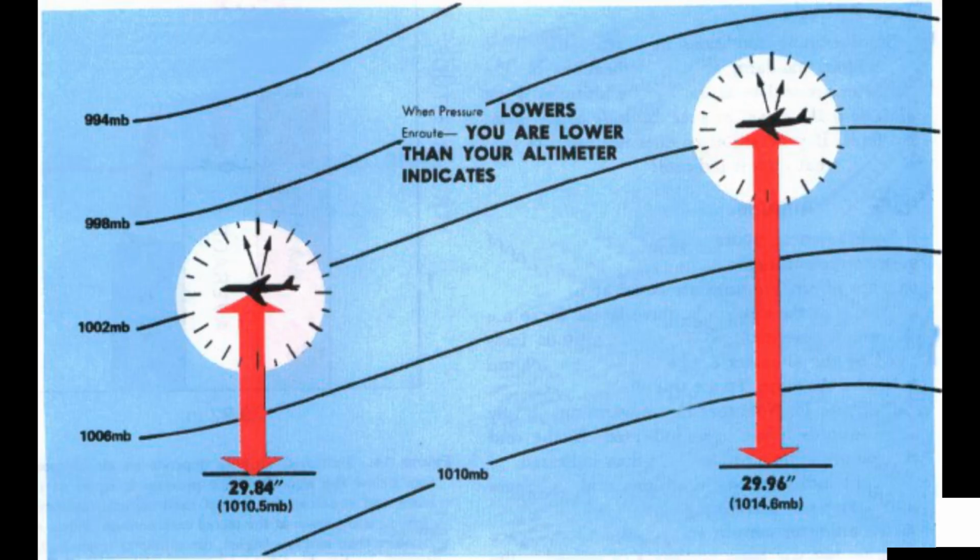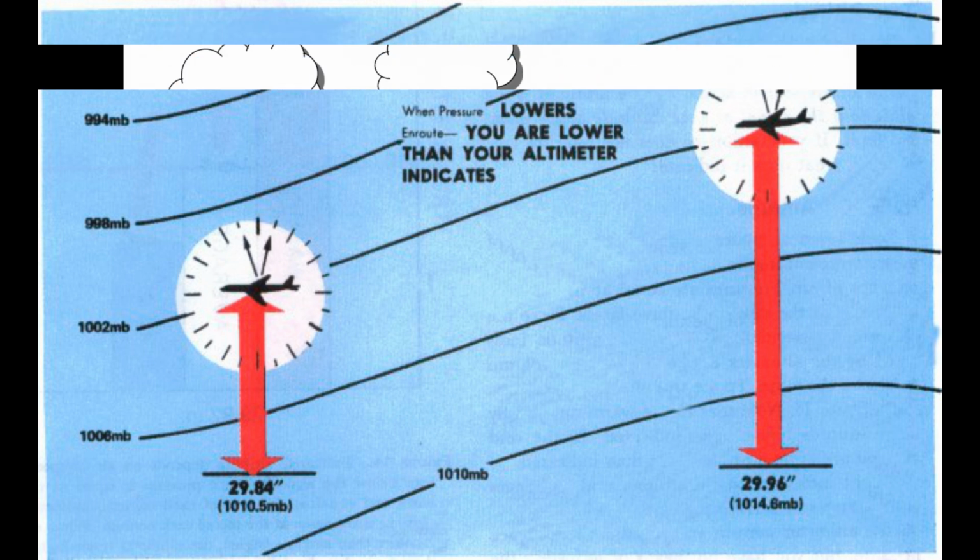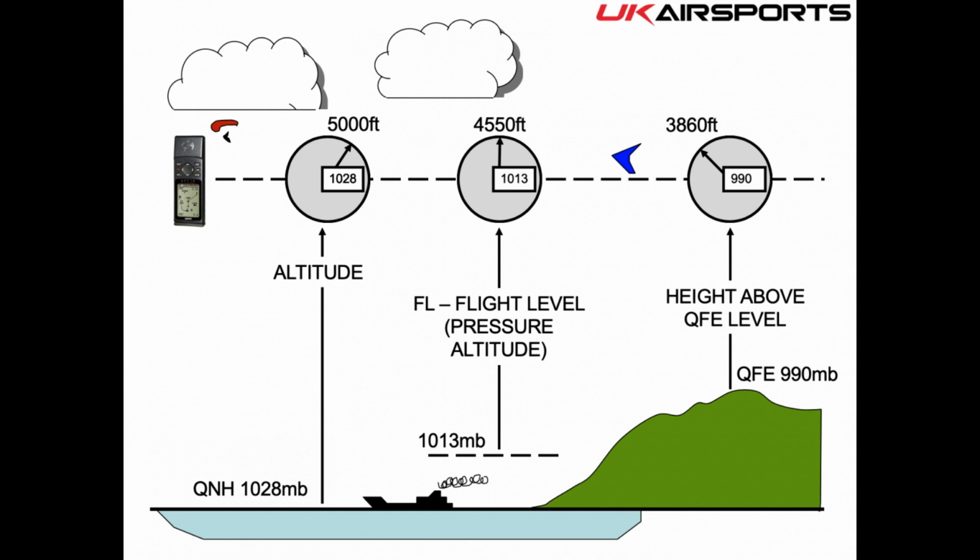Current altimeter setting. 1. 29.92 or higher. Lowest usable flight level, 180. 2. 29.91 to 29.42. Lowest usable flight level, 185. 3. 29.41 to 28.92. Lowest usable flight level, 190. 4. 28.91 to 28.42. Lowest usable flight level, 195. 5. 28.41 to 27.91. Lowest usable flight level, 200.